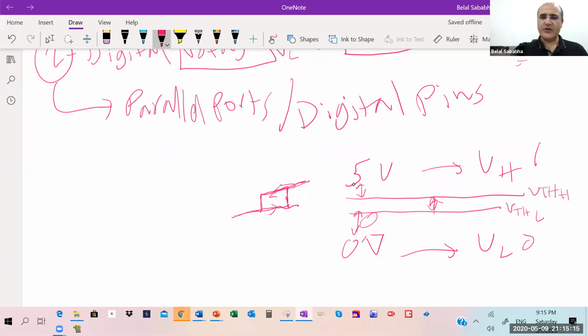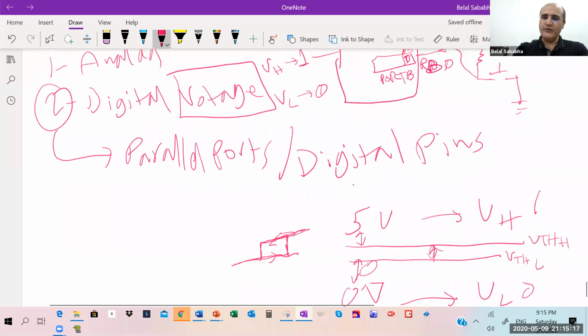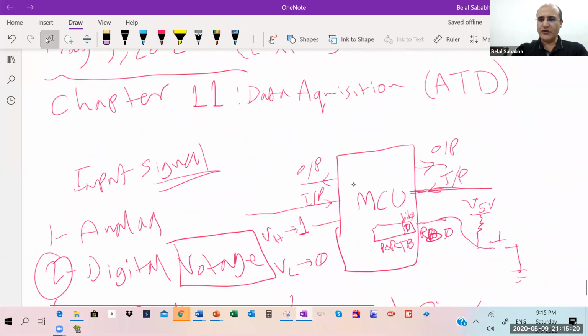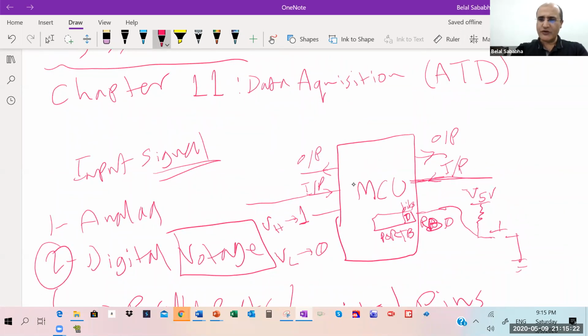Yes. Okay. So the controller, if you bring a voltage from any voltage source, either 5, 4, or 3.7, all of this is the same to it. It's a 1. 0.0, 0.1, 0.2, 0.4, 0.5, this is to it a 0. Okay. So binary 0, 1. Clear, right? This is digital signals, digital voltage.